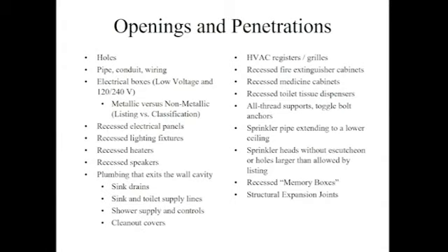Other such things, recessed fire extinguisher cabinets, very, very common, or semi-recessed. And so they make rated ones. The rated ones are actually a component of a fire stopping assembly. So if you go look up under Larsen's or any of the other manufacturers that make them, you'll find that the product itself is actually not rated on its own. It's actually part of a fire resistive or a fire stopping assembly.